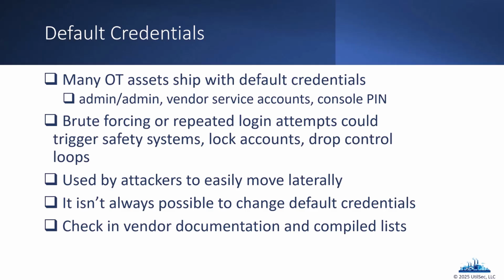So that's why there's a lot of times, right, in OT, we don't enable those additional security features because they could cause operational issues or even safety issues down the road. So that's why you see a lot of default credentials and other quote unquote easy to exploit situations. There are some systems, and these are typically the older ones, where you can't actually change the default credentials. It is what it is. Good luck. Right. So we have to wrap compensating controls around it.